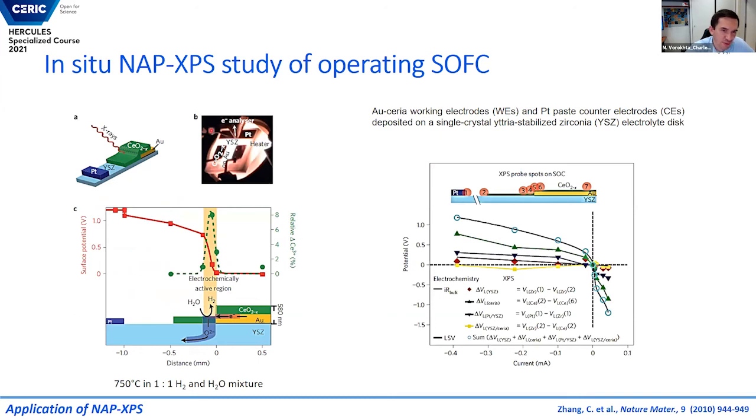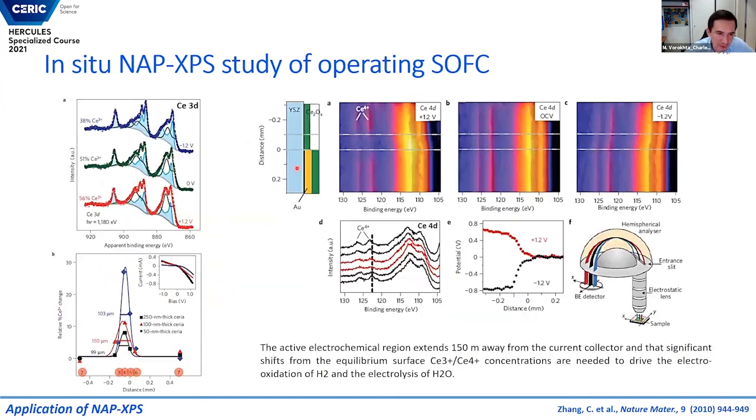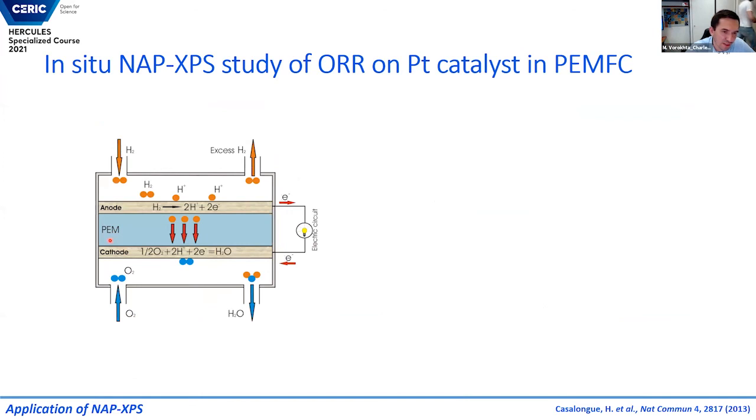So you see that the sample is already completely red. In this case, you work at a temperature which is not higher than 100 degrees C. And here you have transportation of hydrogen to the cathode side, and this is called the hydrogen oxidation reaction, when you oxidize hydrogen.